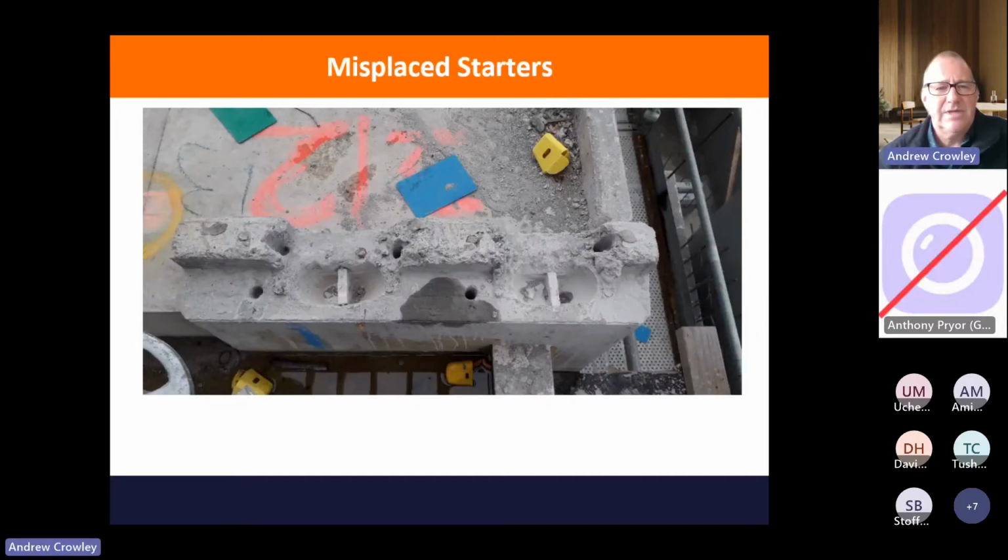And remember the issue with the mold face versus the trowel face. Well, one of them got mixed up and we had a perfect mirror with all the bars in the wrong places. So the old bars were cut out and new bars were grouted in with epoxy. Can be done, would rather it wasn't done, and it takes time, delays the project.